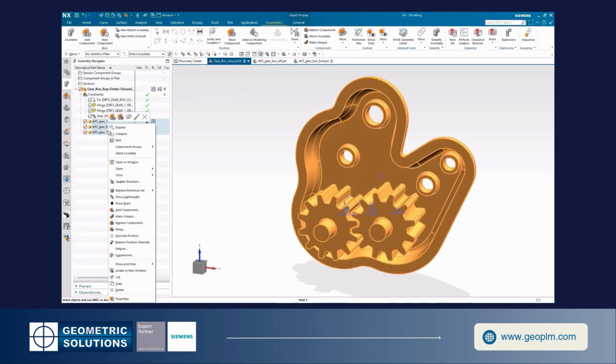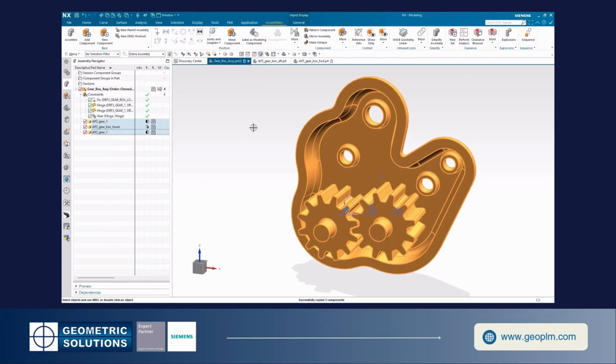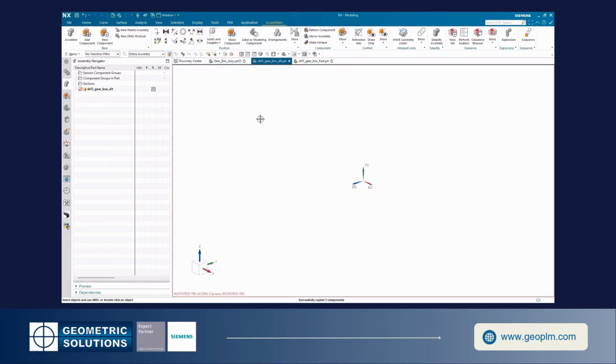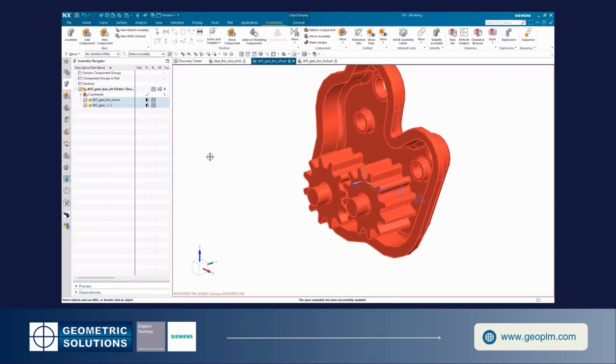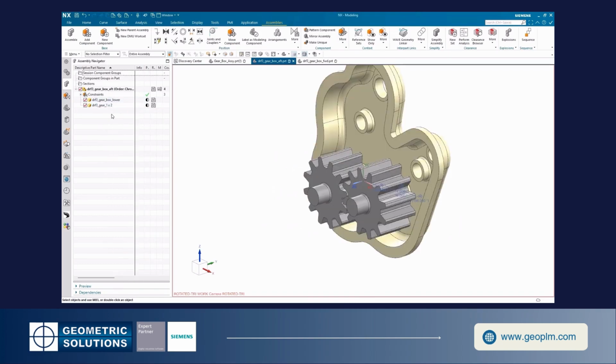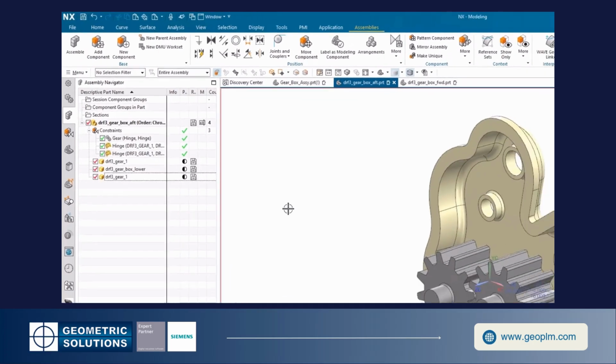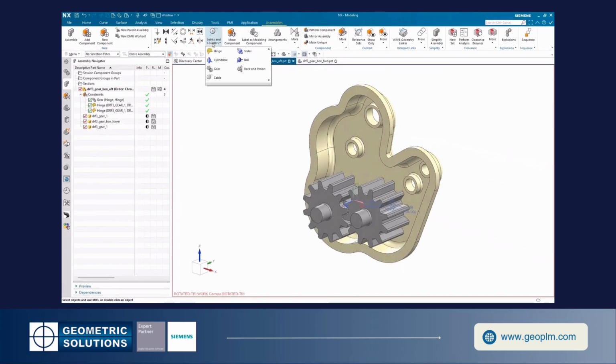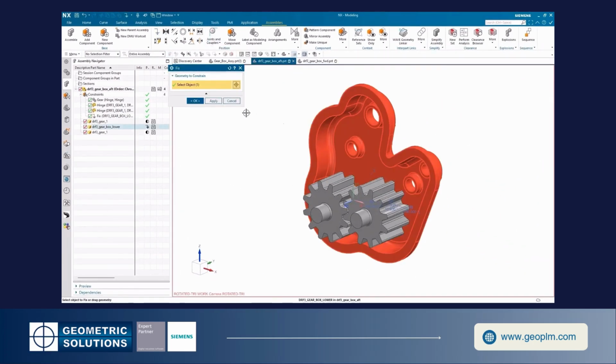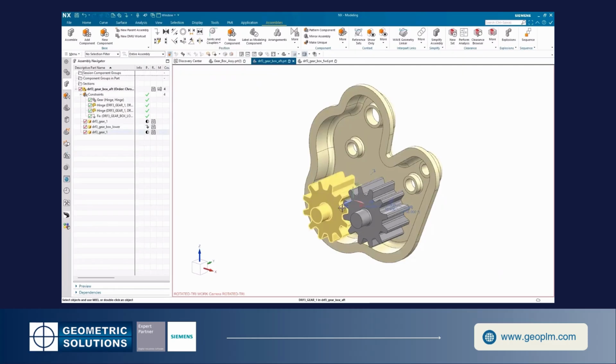Let's copy all three of these components into a different file. Two hinge joints and a gear coupler are copied and pasted into the new model, so all of these automatically come across. To see the relative motion of these two gears again, I just need to fix the position of the gearbox, then NX will resolve the relative motion of the gears properly.